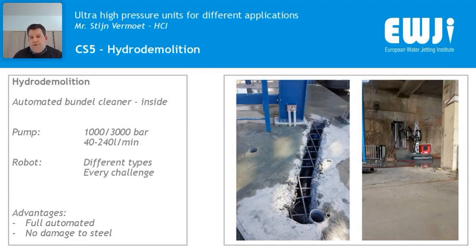Water again is here a big advantage because you don't have any dust. You don't get any damage to the reinforcements. The healthy concrete stays where you want it. So it's a very efficient system to remove concrete from different setups.